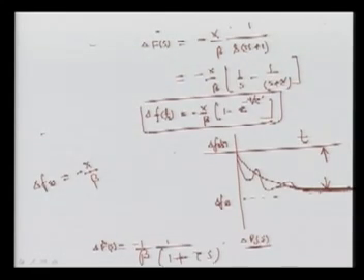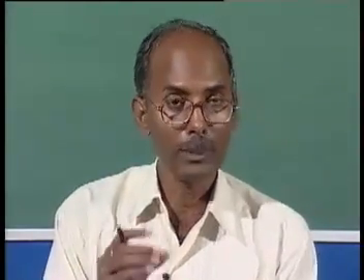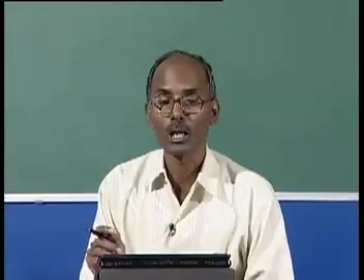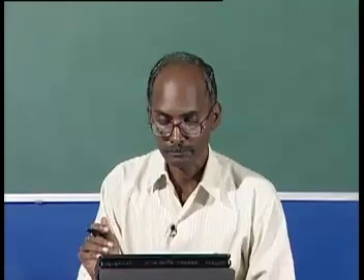So always we are getting one steady state error, that is FSS, which is not required. Hence we have to use another secondary controller. So this loop is called the primary control loop, where the steady state error exists. We have to design some controller, which we'll see in the next lecture, and for that the error must be reduced. Our primary objective is that the frequency should go back to its normal value.